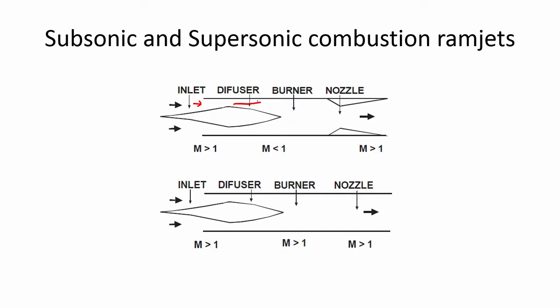So, in the ramjet, by the time it enters the burner, the series of shock trains, even if there might be a normal shock also, have reduced the Mach number to less than 1. Okay. As you know, downstream of a normal shock, the flow is always subsonic. So, if a normal shock is formed anywhere inside this engine, the flow downstream of that is invariably subsonic. So, this is essentially a ramjet. In a ramjet, this series of shock trains ensures that the incoming supersonic air is transformed into subsonic flow by the time it enters the burner.